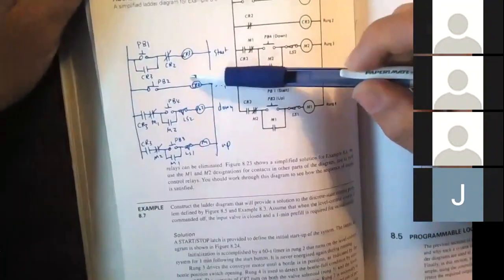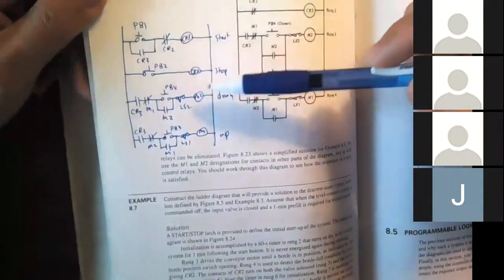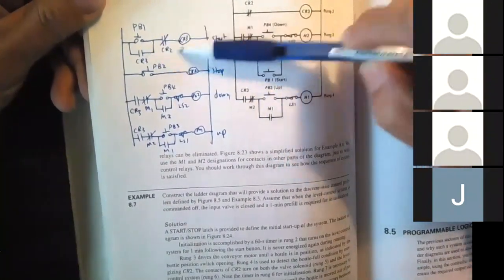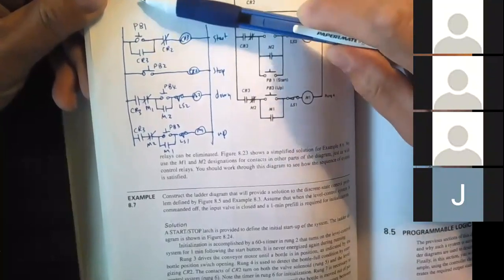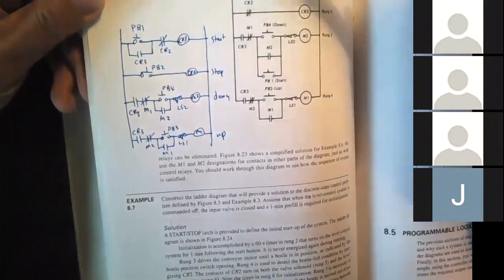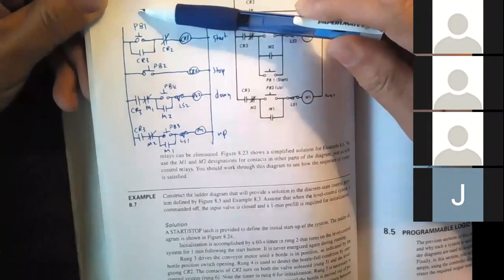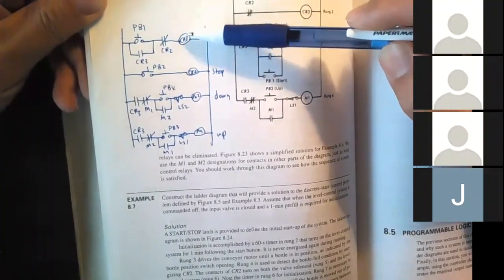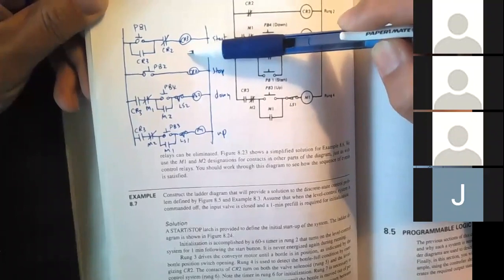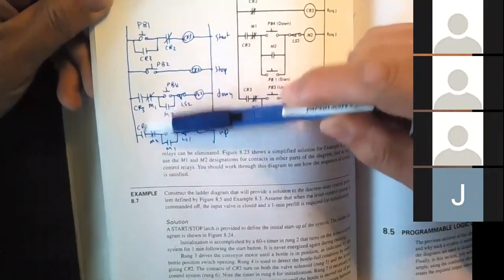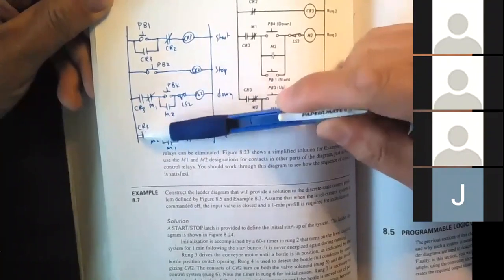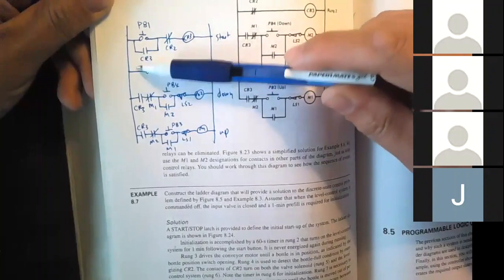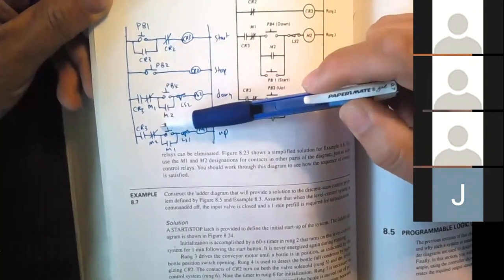So what I'm doing here is my design. My design is in the blue. Here is the start latch. So when I push the start button, I will not turn on any motor. All I do when I push start is energize CR3. Turn the power on. CR3 is the power. So CR3 will turn on, and I will provide the power. I may even put 1 here, but not necessarily here.